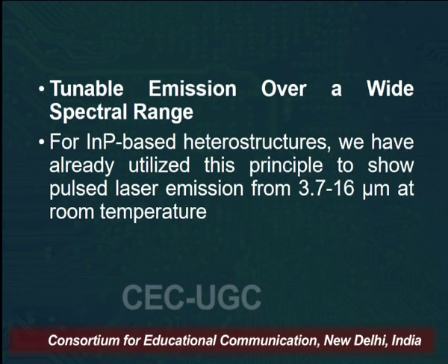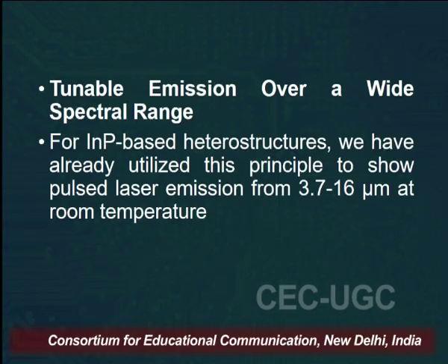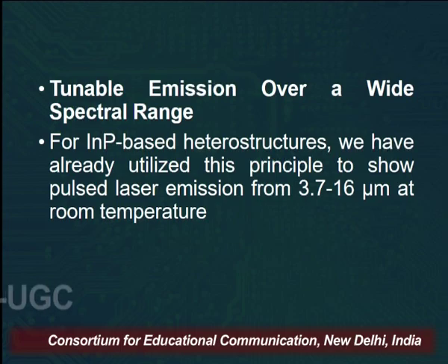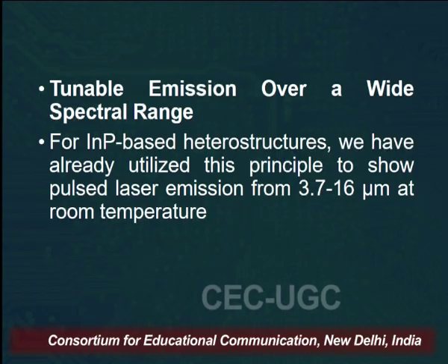So, tunability we can get through this quantum cascade laser. Tunable emission over a wide spectral range is possible, the range being 3.7 to 16 micrometers. At room temperature it is possible.